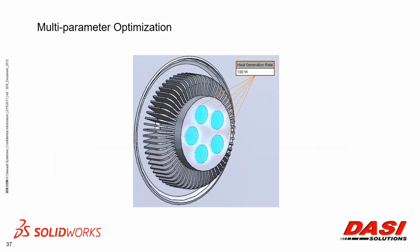In this case, to make it a little less abstract, we're going to optimize this heat sink. Here I've got LEDs. I'm going to generate 100 watts total, and I want to play with the fin design. My goal here is to minimize the mass of this thing, because maybe I need to produce thousands of these things, so try to save a little bit of cost, minimize the mass of it. And my constraint is to make sure the temperature stays below, say, 85 degrees C. Okay, I'm not allowed to go above that temperature.